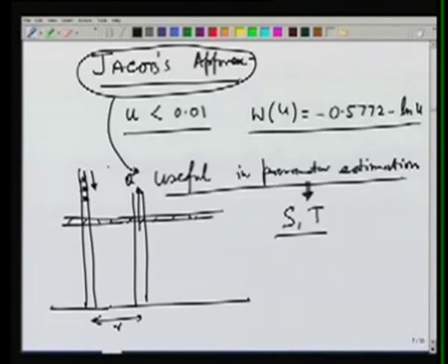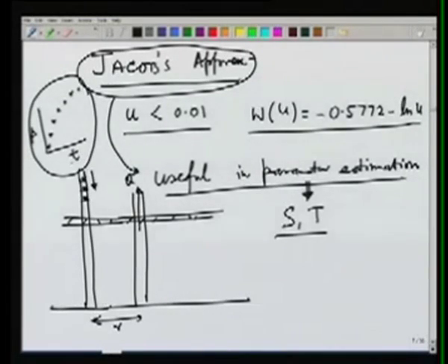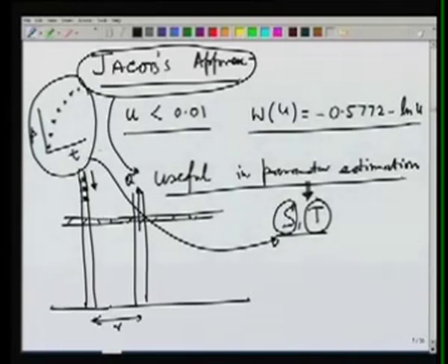So with time, the drawdown s will increase, and using these t and s values, we want to estimate the parameters S and T. So that is what we will look at next, how to estimate or compute the values of storage coefficient and transmissivity from a given observed set of data for drawdown at a well which is located at a distance of r.